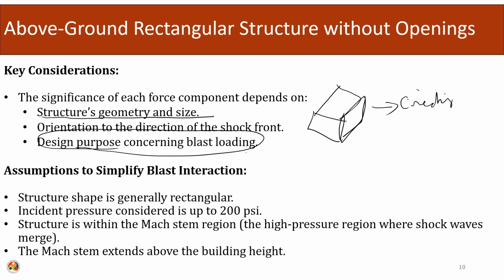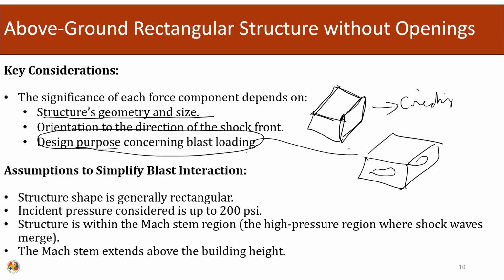For example, in a nuclear containment structure, we will design for a performance level where cracking does not occur. If this is a bunker type of structure, then we will design it so that there is no splintering, no fragmentation. So different design performance limit states depending upon the use of the structure can be fixed here. We have to take into consideration all these points.